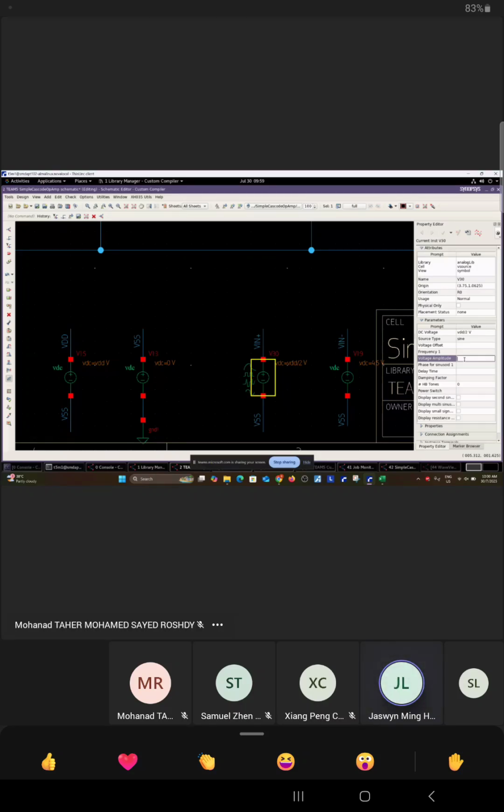So in this case, most likely you see you begin with more or less flat, then slowly curve upwards, become linear, then it will slowly become flat again. So you want to operate in the linear region. Yeah, a linear relationship between output and input. So if you can determine that the x-axis range is from 5 to 50 volt, then you are really succeeding already.